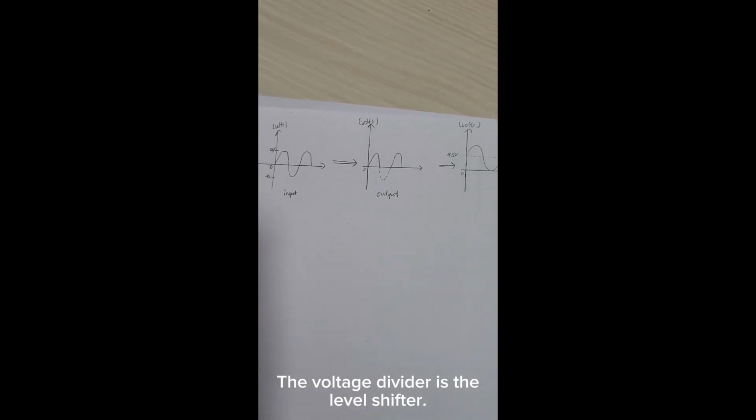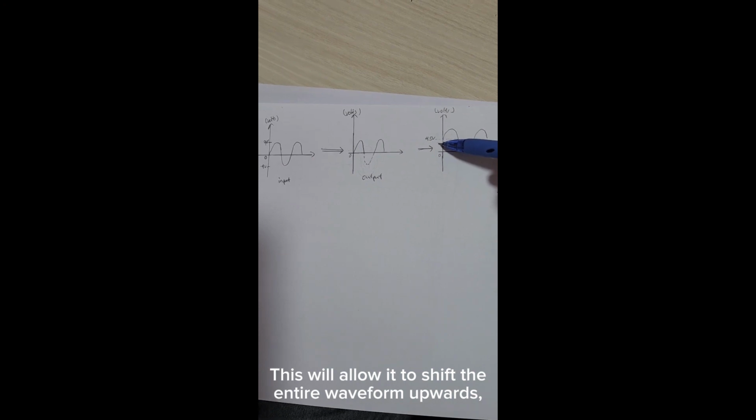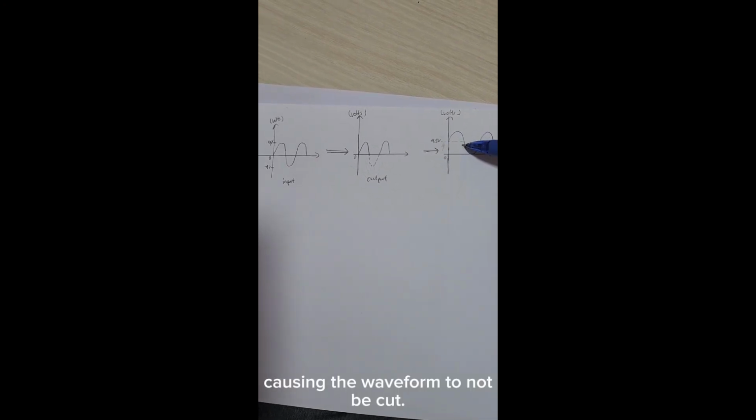Since a single supply mode will cause the negative side of the waveform to be cut, the voltage divider is the level shifter. This will allow it to shift the entire waveform upwards, causing the waveform to not be cut.